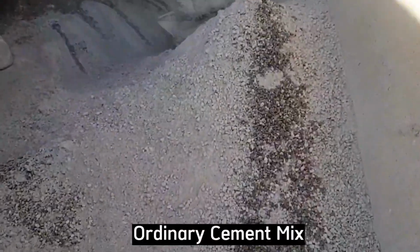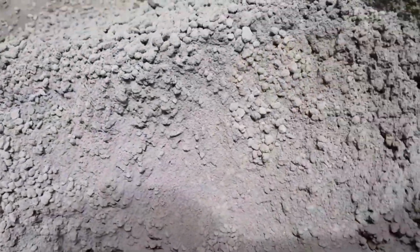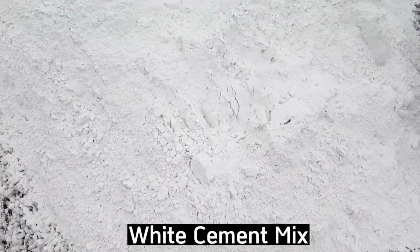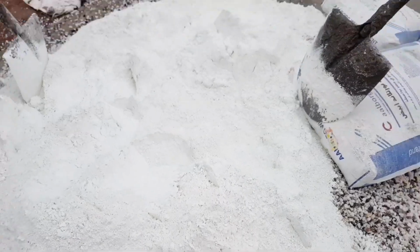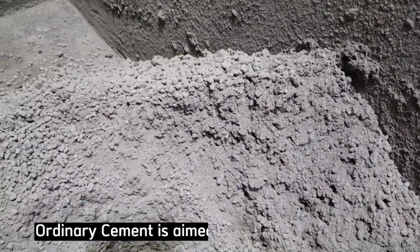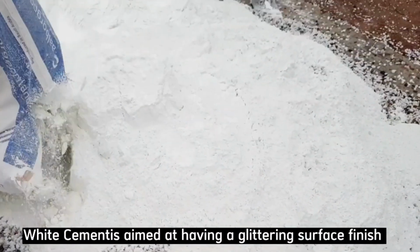For example, when doing terrazzo flooring for a busy shopping mall or arcade, or areas exposed to harsh environmental conditions, use ordinary cement. Then if the priority is design and creating something appealing to the eye, use white cement in the mix. In summary, ordinary cement is aimed at strength, whereas white cement is aimed at having a smooth glittering surface finish.